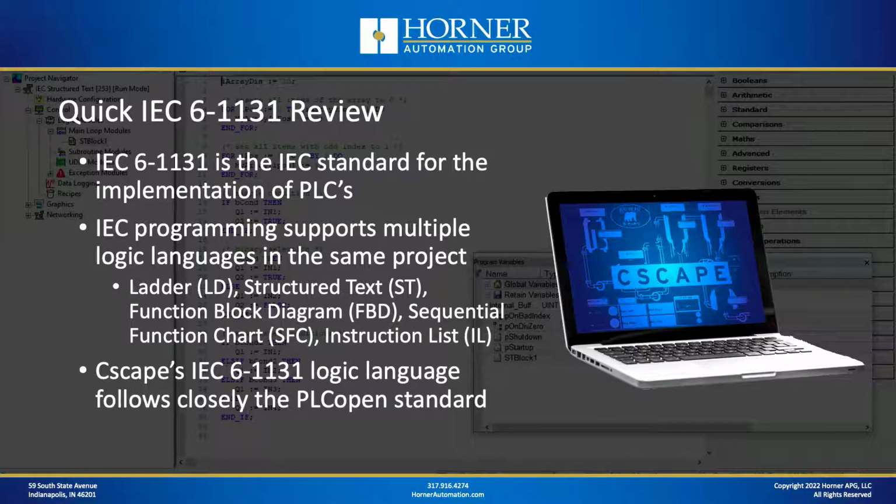IEC 61131 is the IEC standard for the implementation of PLCs. Now, IEC has some advantages. I believe the biggest advantage is the fact that it supports multiple logic languages in the same project. So you can use different languages to do different control tasks depending on which is best suited. Now, last week we talked about ladder. This week we're talking structured text. And over the next couple of weeks we're going to talk about function block diagram and sequential function chart.